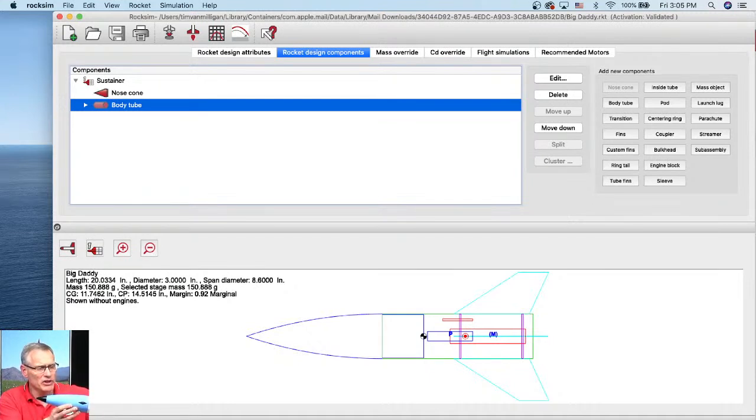The downside of Kevlar is that if you choose the wrong delay, you can rip the side of your tube. It's called a zipper. Typically it happens when the rocket is coming downwards. If your rocket is pointing down, the nose cone comes off and comes up to the side, and it's taking that shock cord and running it right up the side, and if it's going fast enough, it's going to zipper it.